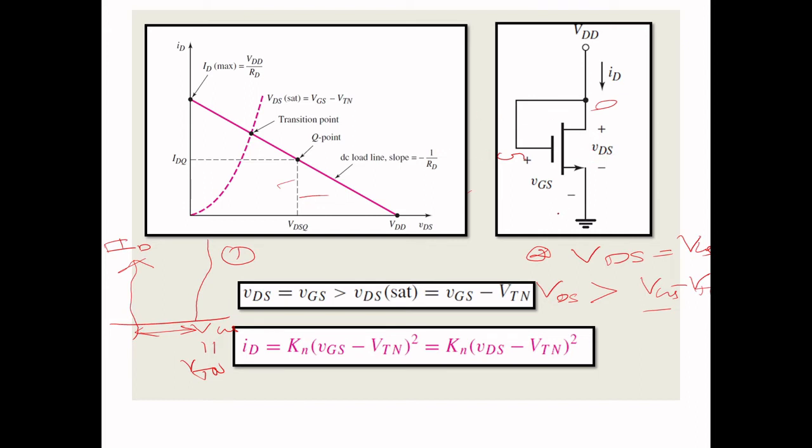Okay, so I'm repeating again the first task. You know the drain current is determined after the threshold voltage, only after generating a channel. With respect to the change of VDS, the ID is changing, right? The second thing is here both gate and drain are shorted. So obviously you should know with this idea the VDS should be greater than VGS minus VTN. When you say VDS is greater than VGS minus VTN, it is forced to work in the saturation region.